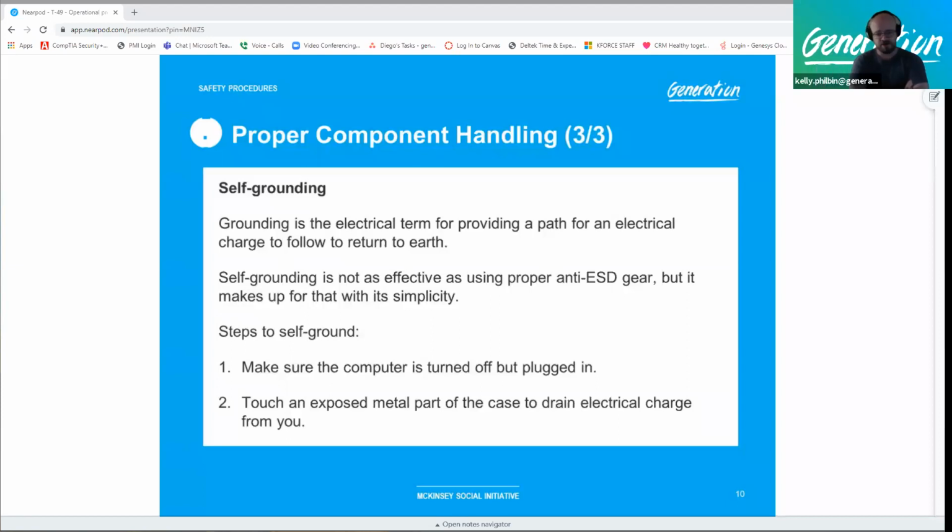It also goes to building your methodologies. When you're going through a troubleshooting process or a repair process, you want to be able to use the same steps every time. That way you do not forget something. Rather than trying to say with this type of device you leave it plugged in, with this type of device you unplug it, just have the exact same procedures every time. That way you don't make a mistake and leave one plugged in that should have been unplugged.